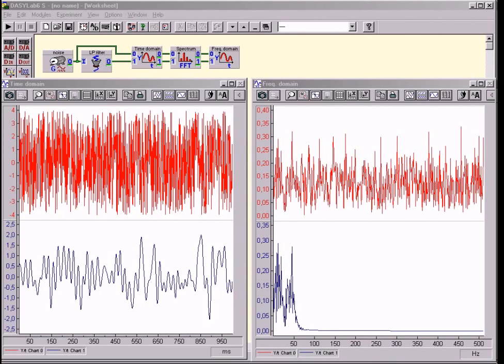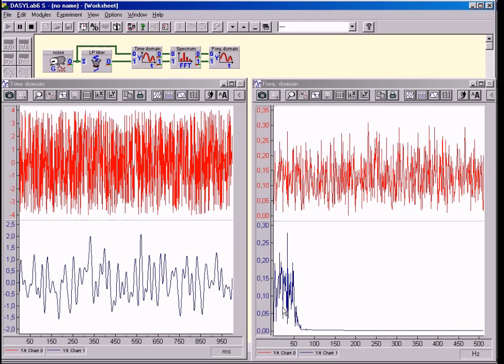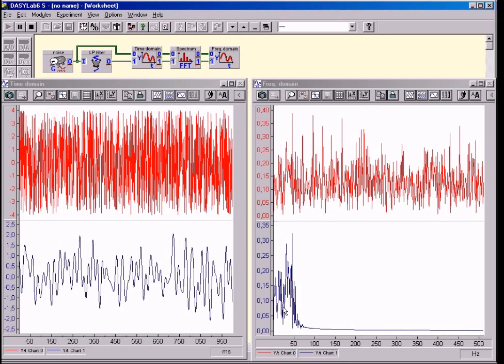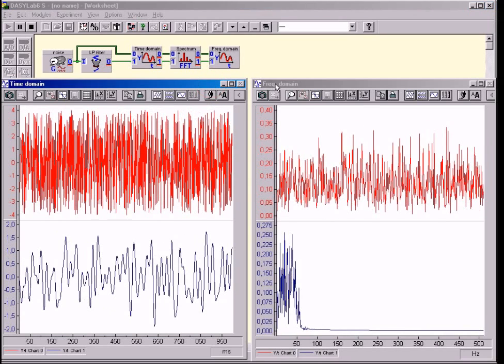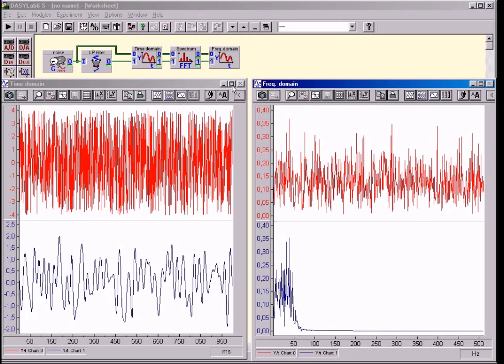A practical consequence of the UP is the lack of ideal filters. Filters are signal technology components which allow frequencies to pass through, conducting state region, or to be blocked, blocking state region. If only the low frequencies, up to a certain limiting frequency, are allowed to pass, this is called a low-pass filter. As we wish to demonstrate, the transition from a conducting state region to a blocking state region and vice versa must always take place with a specific uncertainty.